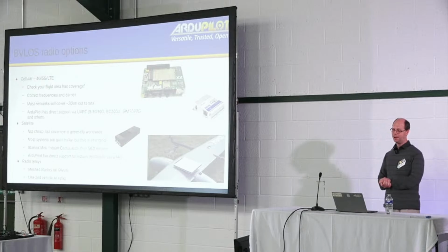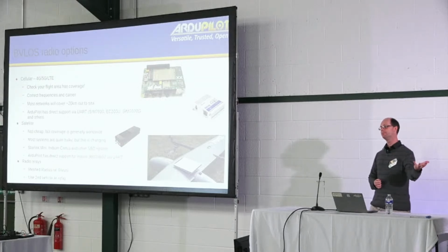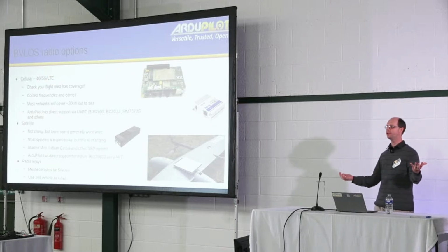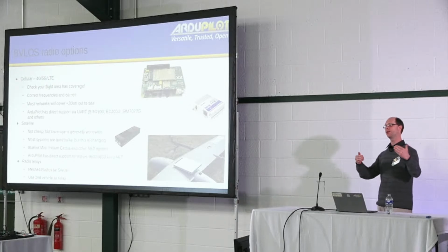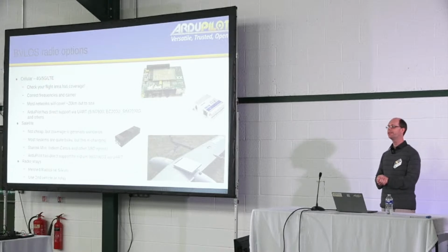Related to that, check the frequencies supported by, on one side, your telco, and on the other side, the modem. Not all modems support all cellular frequencies. Not all carriers support all cellular frequencies. So make sure that you've got the right match there. Related to that, you do tend to want to use the lower frequency bands for cellular systems. Sub 1 gigahertz is really nice.